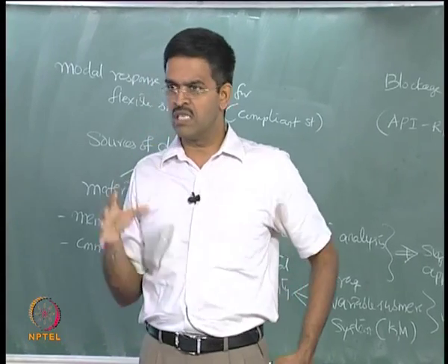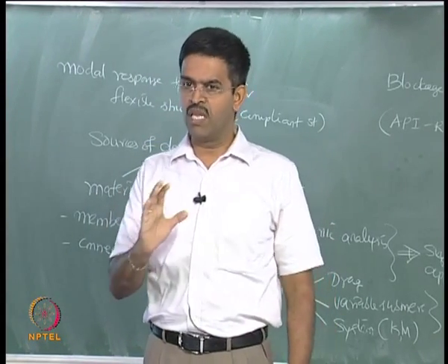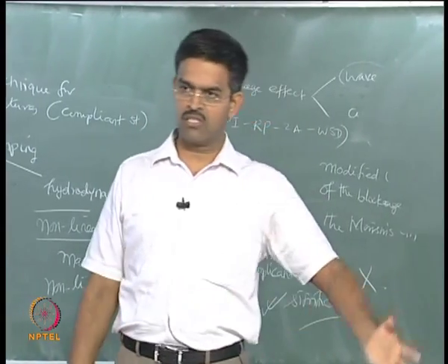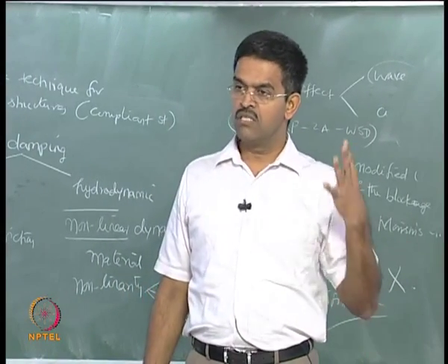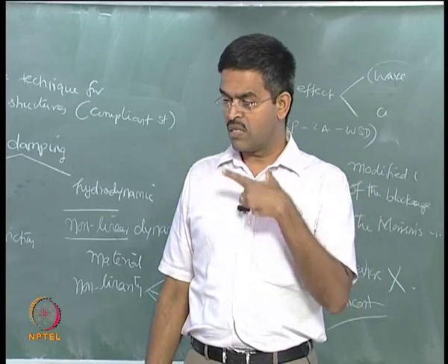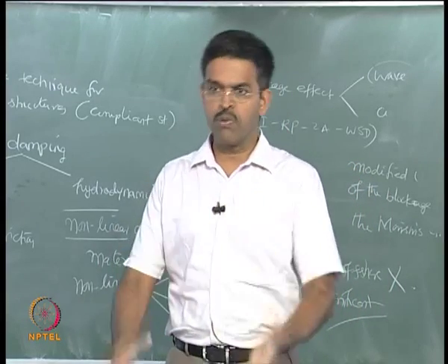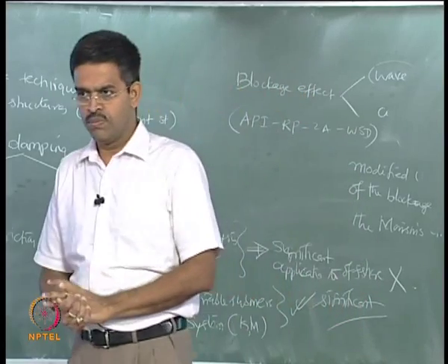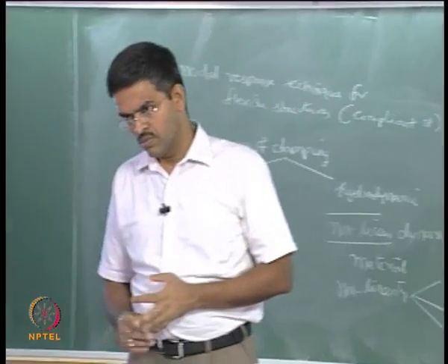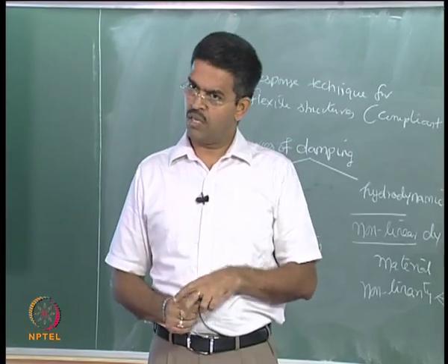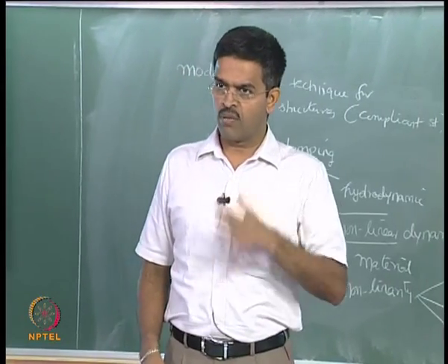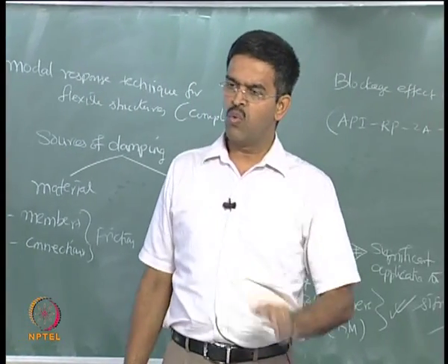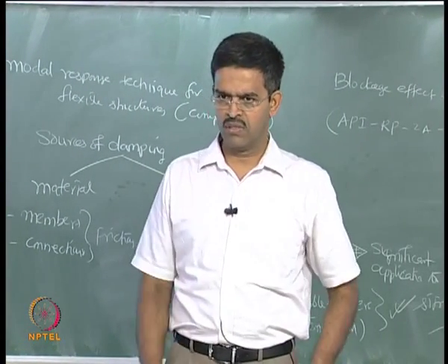So I am not interested in estimating the forces, remember it is very important. What is the fundamental difference between dynamic analysis of ocean structures and land based structures is that in land based structures stresses and forces are important, whereas in offshore structures we are talking about the response. You may wonder why, can you tell me why it is so? Of course moments and forces and stresses are important, but most importantly it is my responses. Can you give me a very defending statement why this is addressed in dynamic analysis of ocean structures, why not the forces?